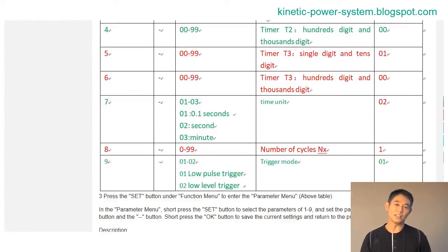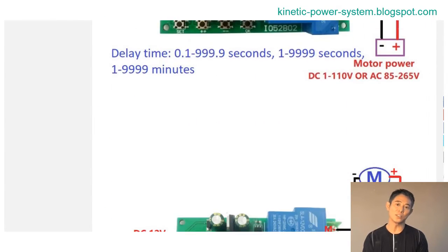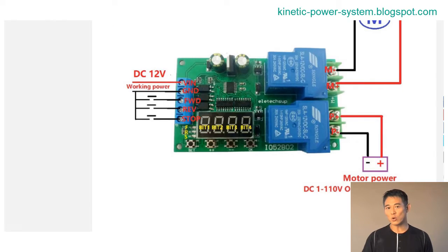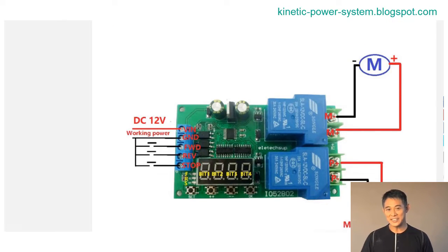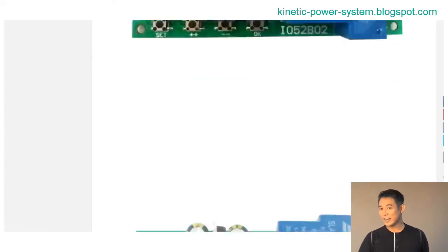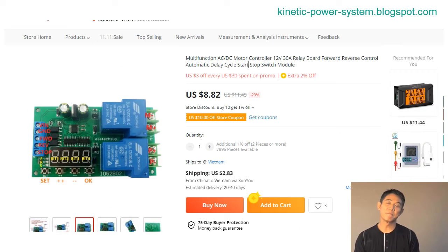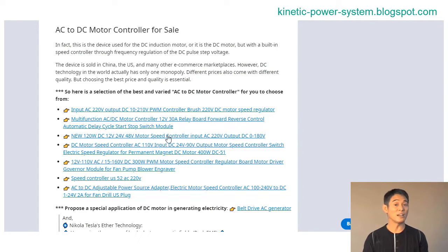What is the difference between a motor driver and a motor controller? The main difference between a motor controller and a motor driver is that the controller is responsible for controlling the speed, torque, and direction of the motor, whereas a motor driver is responsible for providing enough electrical power to the motor as required. When would you use a motor controller?